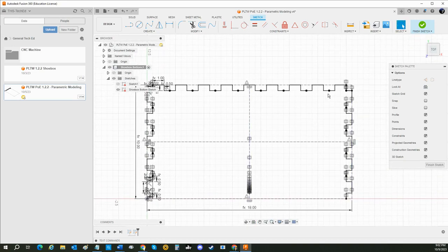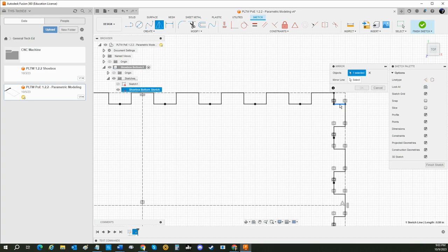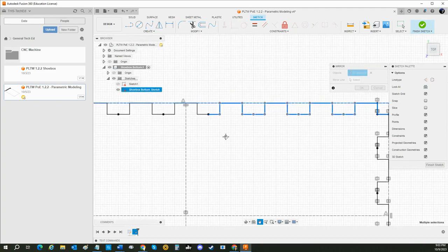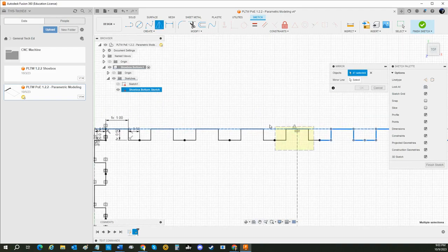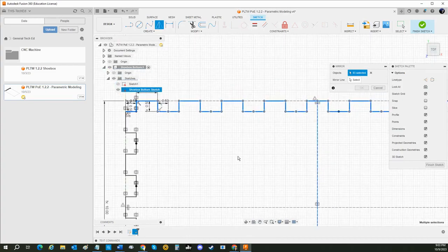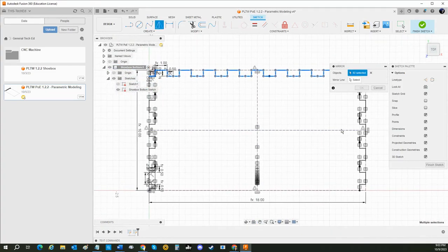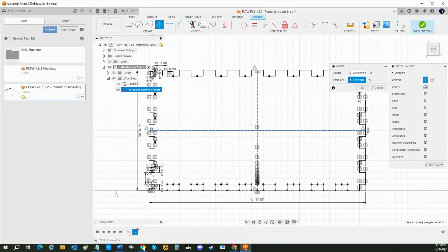And I will now do this across the top. So I'm going to mirror. What is it I'm mirroring? I'm going to mirror this, this. Grab all that. Let's grab all this. This one and this one. Select that again so it goes away. My mirror line is right here. It's going to show up at the bottom, which is what I want.